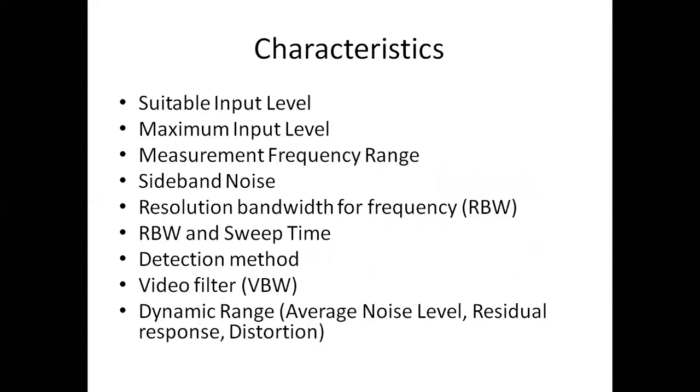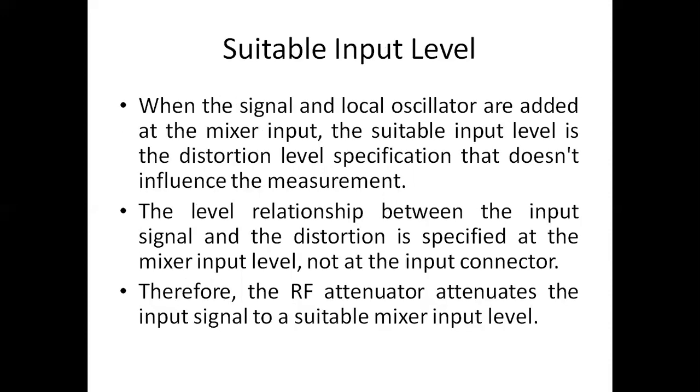So there are 9 characteristics: suitable input level, maximum input level, measurement frequency range, sideband noise, resolution bandwidth for frequency, RBW and sweep time, detection method, video filter, then dynamic range. So the first one is suitable input level.